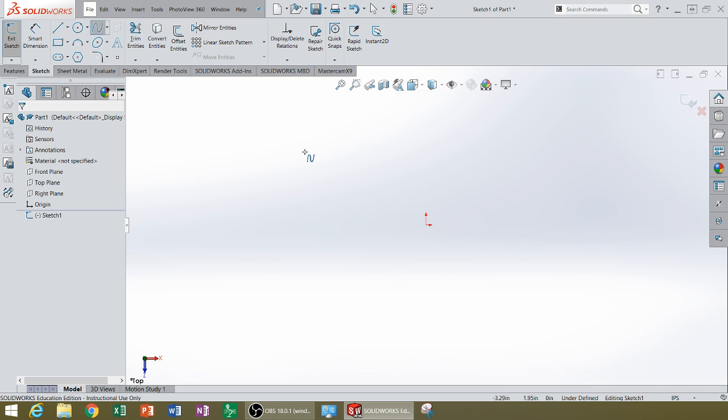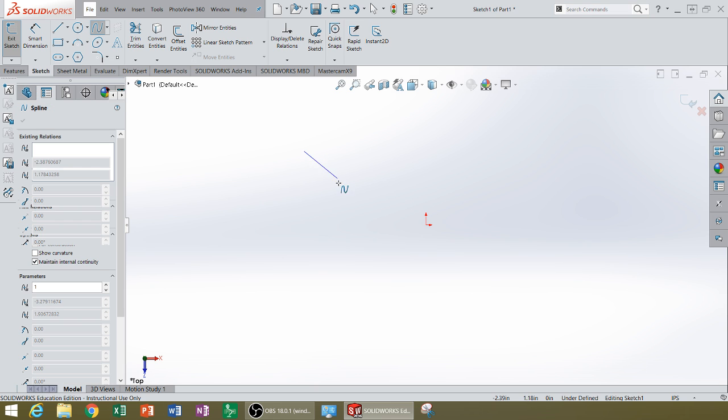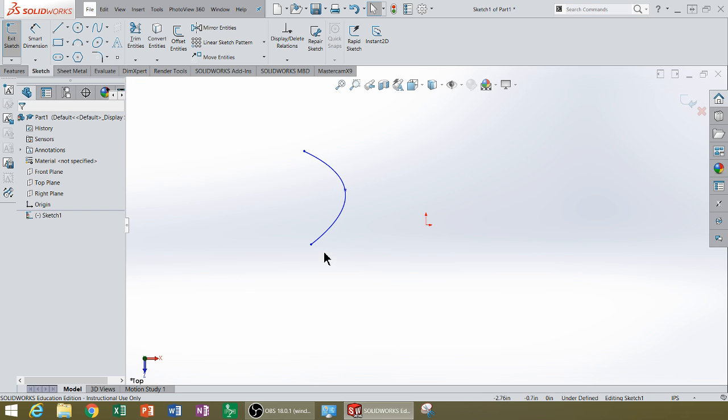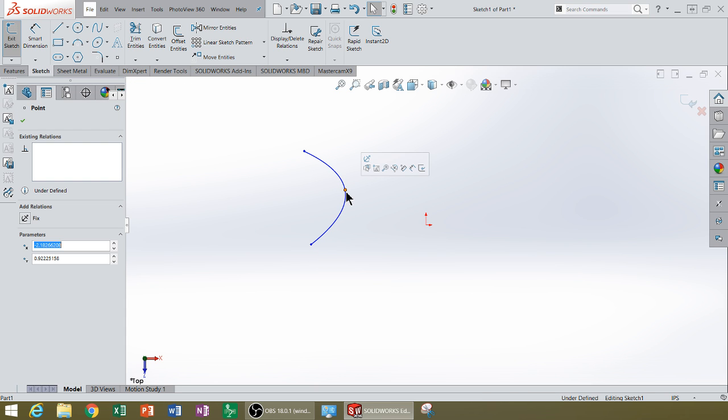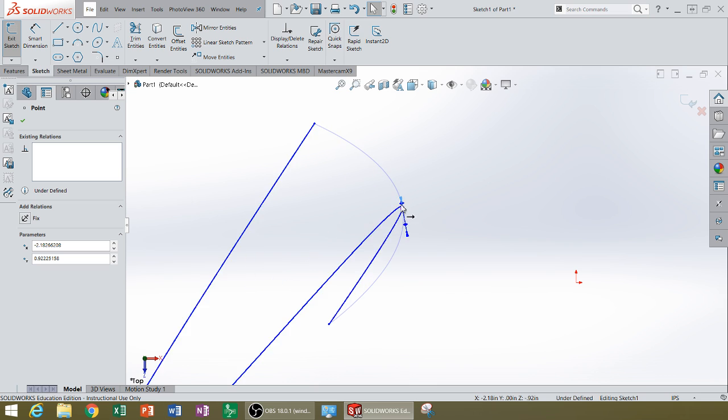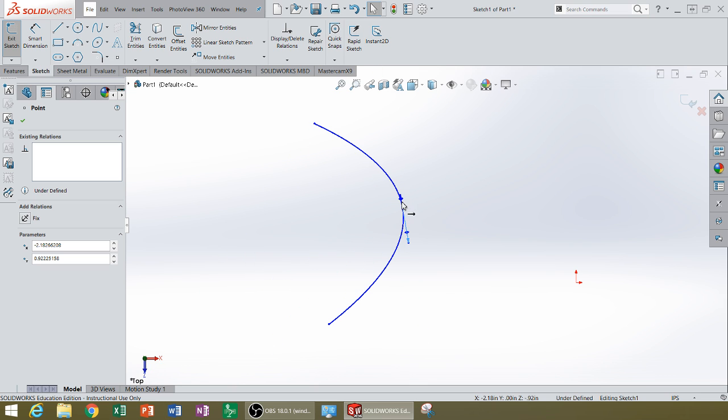And I'm going to go ahead and drop 0.0, 0.1, and 0.2. So I've got 3 points on this spline. And then I go select. You'll see that as I click on each one of these points, I get what are called handles. And these handles do two things. They control the tangency direction and then the bias of the end of that spline line.